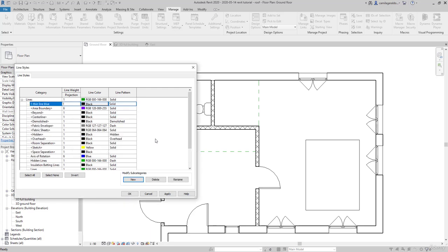In conclusion, if you want to use your personal line styles, I recommend to create a bunch of them, just the ones that you need, of course, and keep the default styles unchanged. And remember that this only applies to the file that you are currently working on. However, a trick to avoid doing this process all the time is creating a template file with all those styles there.